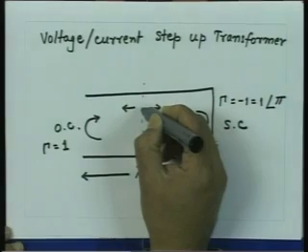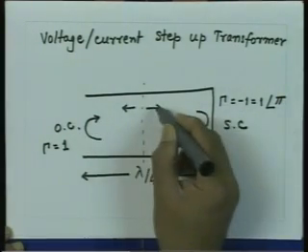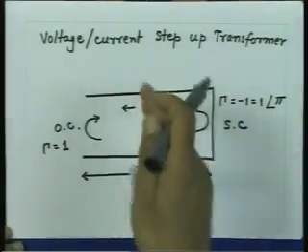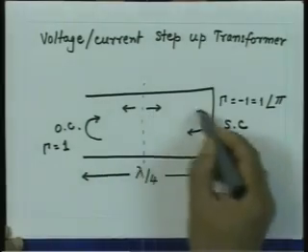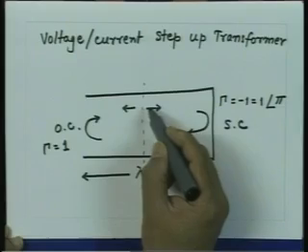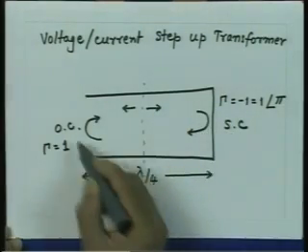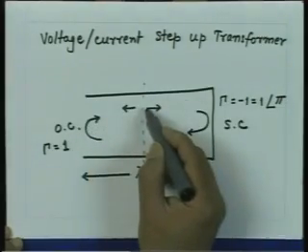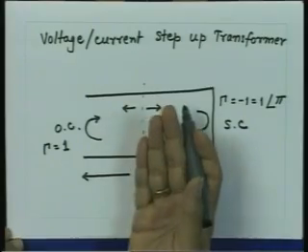That means the reflected wave has the same phase as the wave which is getting excited, or in other words, some kind of positive feedback is going on. The induced voltage and the voltage after the round trip add up. So, the two voltages together start travelling. When they come back after a round trip, they are again in phase, so the induced voltage again adds to this voltage. The voltage essentially starts growing on the transmission line.